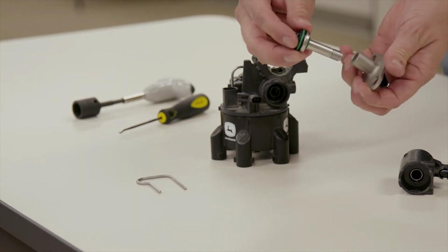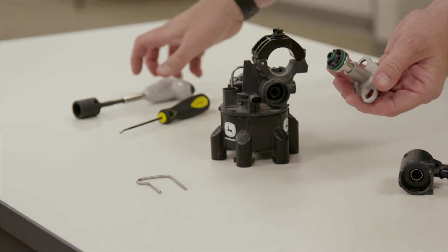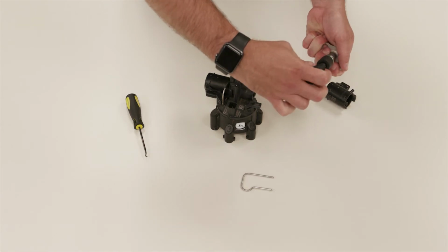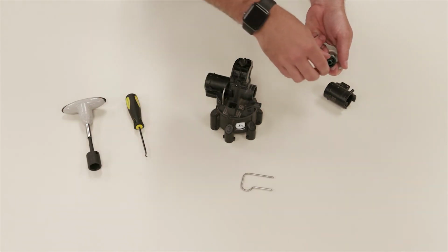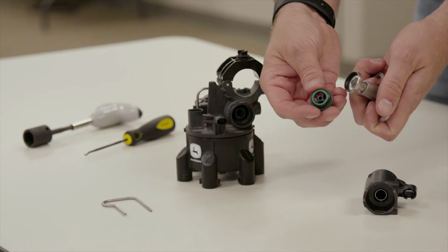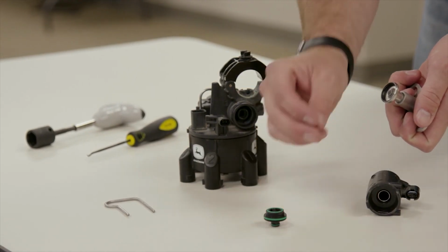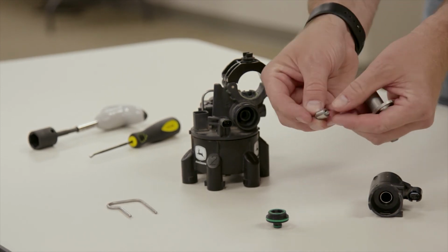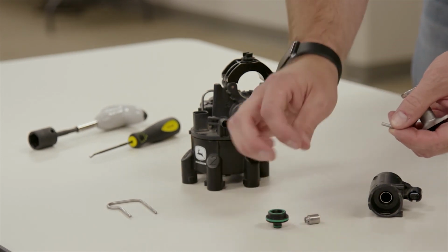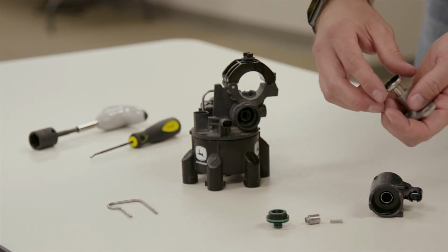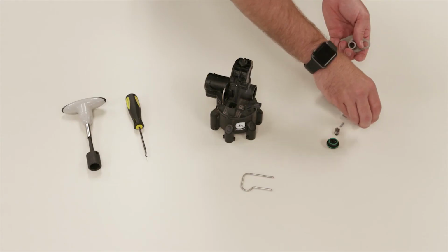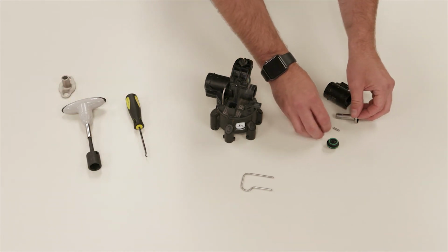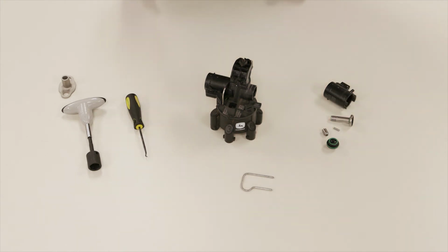Now that cap, we want to make sure that we do not use any pliers on it. So we use a special tool here along with a special torque wrench provided by Deere. We loosen that cap and remove it. Inside there's another O-ring and also the part that's actually doing the pulsing. This part goes back and forth, and you'll notice the spring in there. We want to make sure that all the components are free of debris and also that the inside of the stem is as well. Keeping these free of debris makes that move freely and does not score the inside of it, which is essential to the movement required for ExactApply.